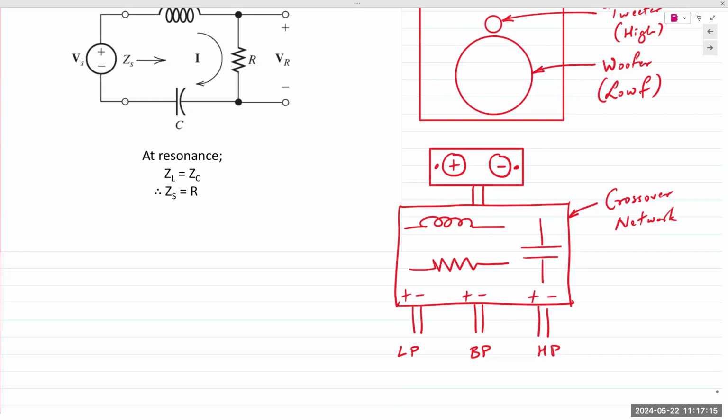So the cheapest speakers, like the small cube speakers you can pick up for 10, 20 bucks, literally have simply a resistor and a capacitor. Less than 20, 25 cents to make those kinds of filters. Slightly higher quality ones, like the ones in this room, I'm assuming they probably cost a whole lot more because they're professional speakers. So they would have an actual circuit board with higher quality components. And the really expensive ones will probably have something like an inductor, a capacitor, and a resistor, to do high quality filtering.